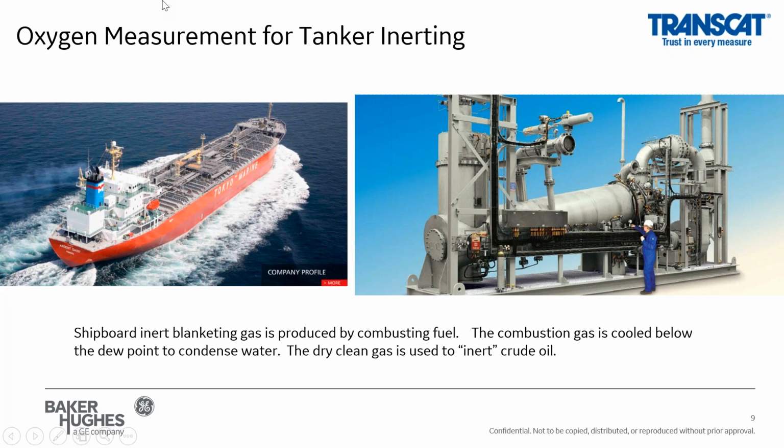One of the big areas that we're involved with is on tankers that are seaborne, fuel tankers, and they produce inert gas on board. They use the product of combustion. So one of the products of combustion, of course, is CO2, and CO2 won't burn. So they clean up that CO2, they use cooling to condense out any liquids, and they actually use seawater for cooling.